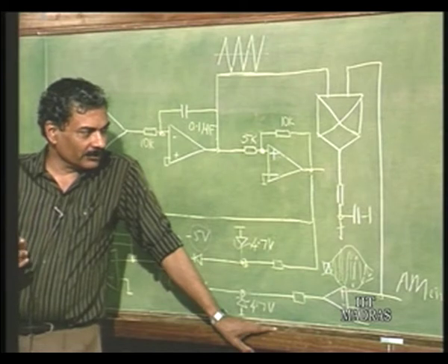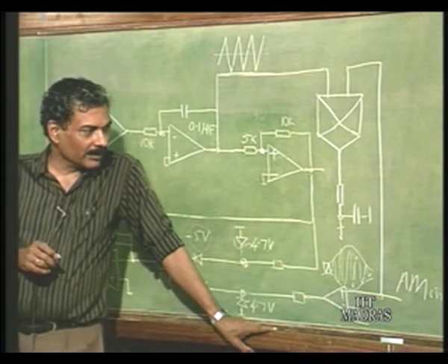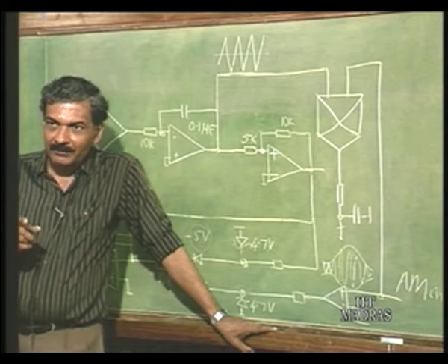So, now you are going to see omega m component on one axis, okay, on one vertical plate, and another one is the AM itself. So, we can demonstrate to you how the depth of modulation, when it changes, the amplitude of the AM detected output will change, and you can see on the screen now that one is the AM waveform, another is AM detected waveform. Okay. That is what is in between that AM waveform is the AM detected waveform. Please change the depth of modulation.